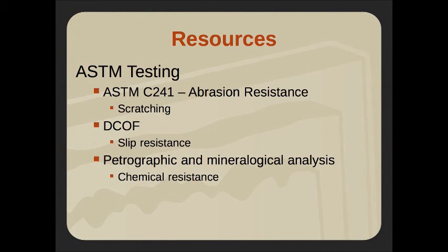Also, in that same regard, the DCOF, or the dynamic coefficient of friction testing, is critical. It's a little bit in limbo with the stone industry right now. Hopefully over the next few months we'll be able to see an adoption of the new tile test that they're doing. I know there's a lot of work being done on that, but it's still something we have to consider, the slip resistance. We've got to meet the coefficient of friction so people aren't slipping. It's a liability issue, right? We have somebody slipping on a floor. We didn't do our homework. We didn't put a hone finish where we should have.